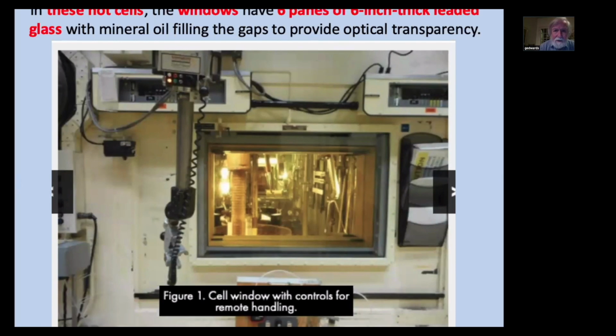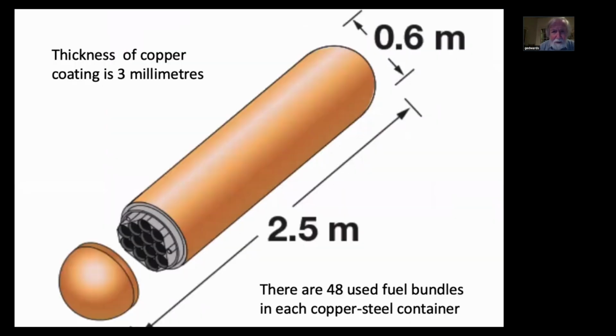In these hot cells, the windows in this case have 6 panes of 6-inch thick leaded glass with mineral oil filling the gaps to provide optical transparency. You'd have to inquire to find out exactly what configuration NWMO has in mind for their hot cells, but those would be a feature of any DGR.